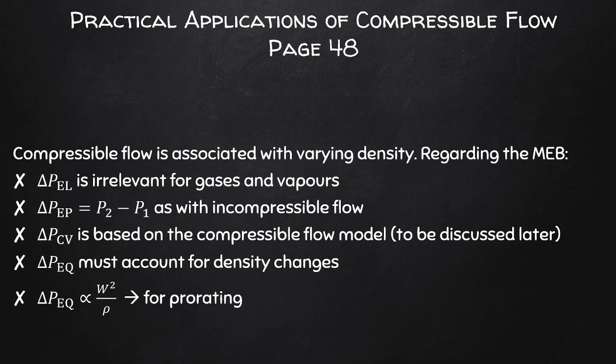Since gases seldom have a density required to cause a significant pressure drop due to the elevation, we tend to neglect pressure differences due to elevation. Okay, obviously the atmosphere is quite tall, and so just by the fact that there's all this height we actually have a significant pressure due to this height of the gas.